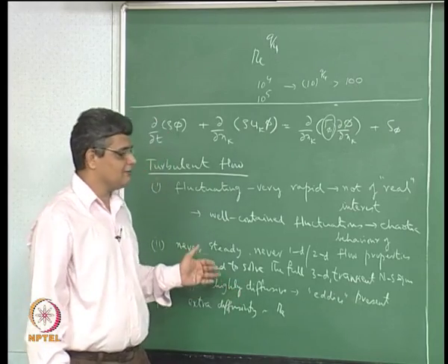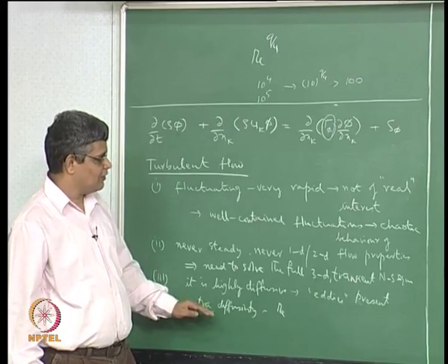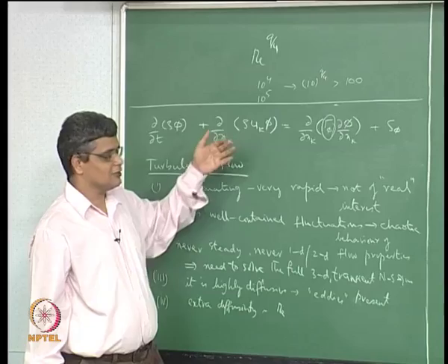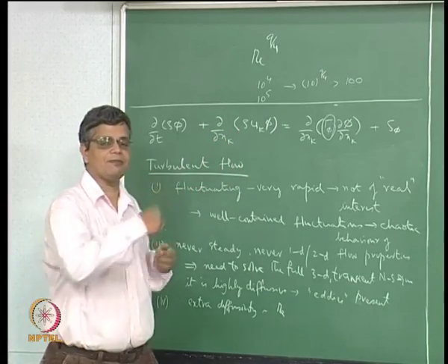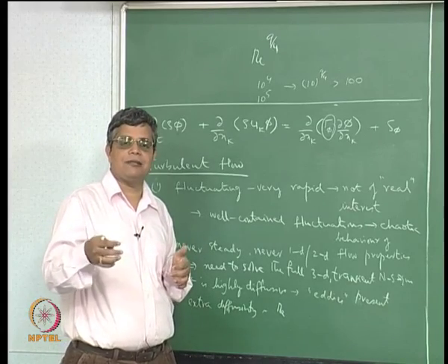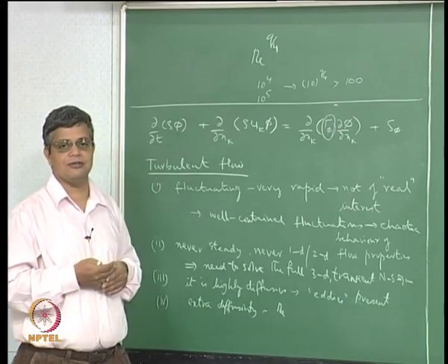So you can have this additional diffusivity, or for example the heat transfer coefficient or the friction factor in turbulent flow divided by friction factor in laminar flow is not a constant parameter, and it can be a factor of 10, it can be a factor of 100, it can be a factor of 1000 depending on what kind of Reynolds numbers you have.